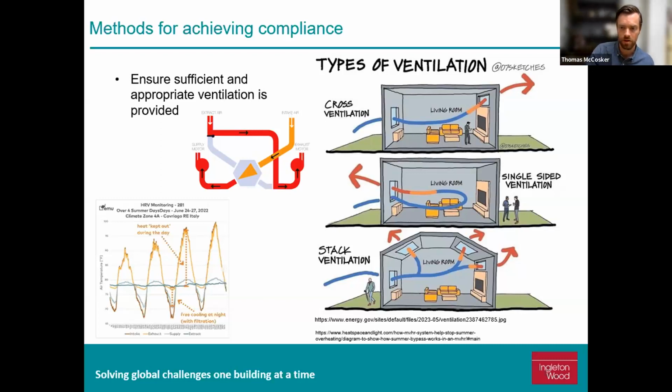It's important here that for natural ventilation, that nighttime ventilation can be employed, and it is particularly important that a summer bypass option for an MVHR system is to be fitted so that we can bring in that cold nighttime air without tempering it. So if you look in the bottom left here, we can see that the intake and exhaust temperatures are relatively high and track with each other. And then as those come through a heat recovery unit, the internal temperatures that are being brought out are tempering that external air and bringing them down to a more tolerable level.